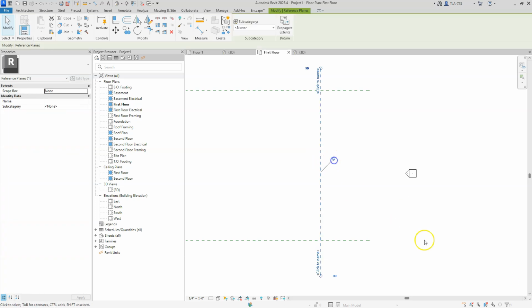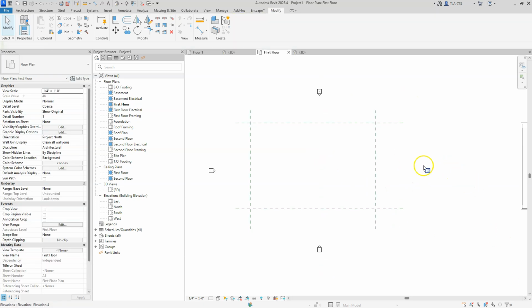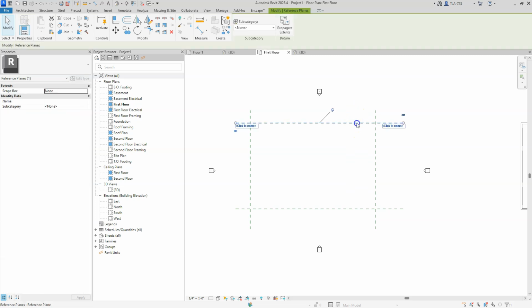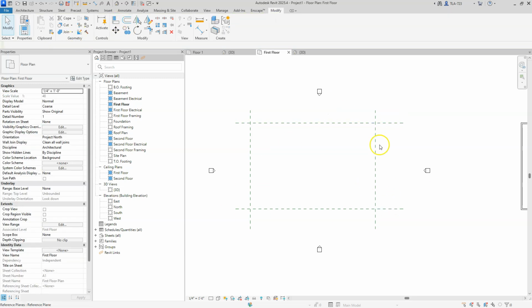Okay, so you can just toggle back and forth between pinned and not pinned. The nice thing about pinning something is it's easy to unpin, but it won't move unless you unpin it. There's no way to move it. If I click and drag it up here, try to move it, try to delete it, anything, it's not going to do it. So it's a nice safety measure. You'd be surprised how many times it's easy to accidentally move something without realizing you're doing it in Revit.